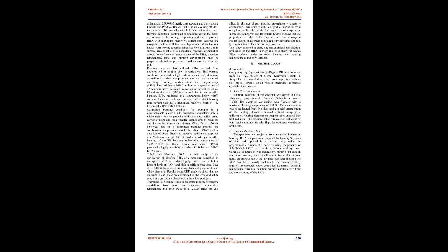Andrea B. et al., 2019, studied the structure of the RHA and found that it has 3 layers, outer, inner, and interfacial, with honeycombed and interstitial pores. These pores are responsible for the high chemical reactivity and large surface area. Factors determining the applicability of RHA as a pozzolanic material are its availability and accessibility of reactive silica sites, which is crucial for the development of durable concrete.